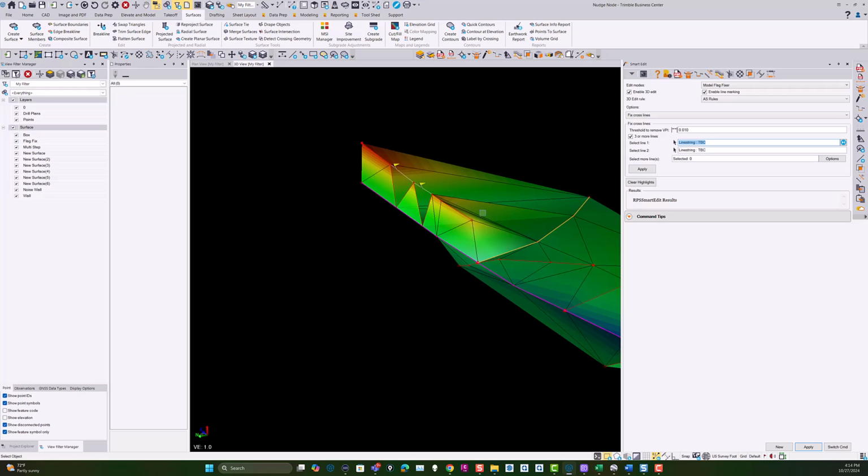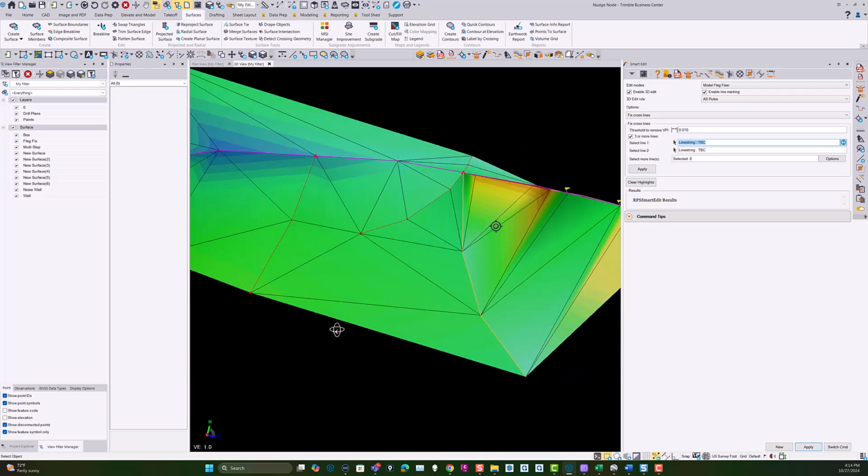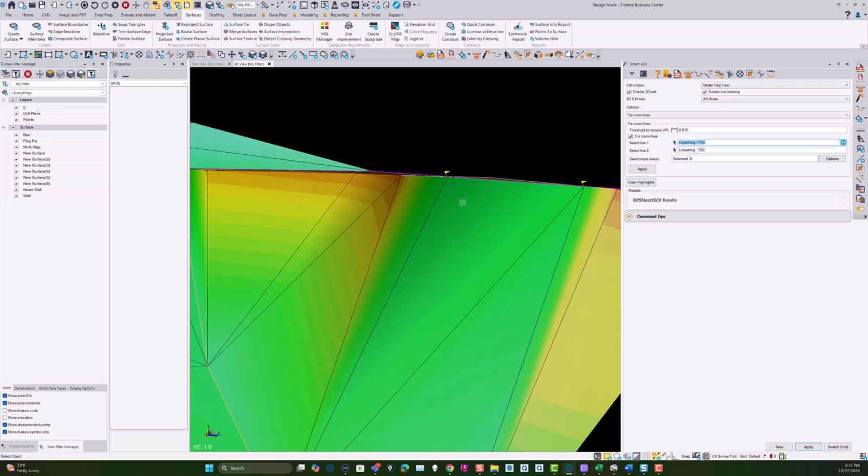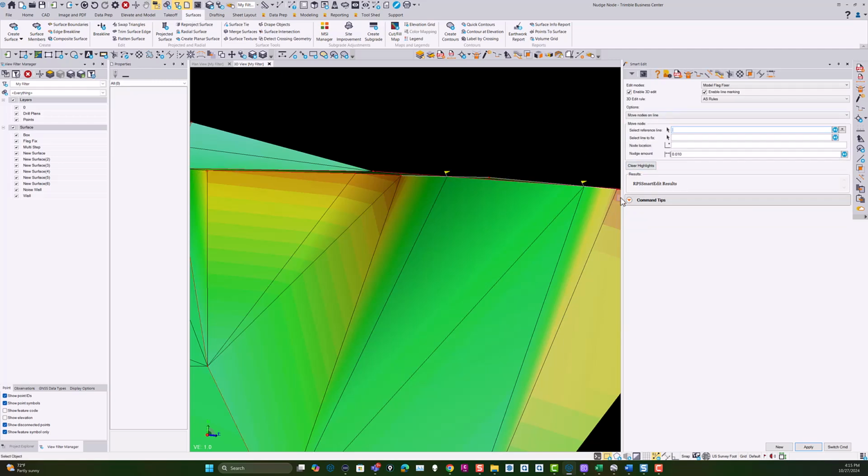Now in this one, this is a very common scenario where you get 2 surveyed lines and they're supposed to be running parallel at different elevations, like a top and bottom of a wall, but just because of where you surveyed the points, you got a point incorrect. So this is what we call move nodes online, and what that allows us to do is pick the line that we want to hold fixed.